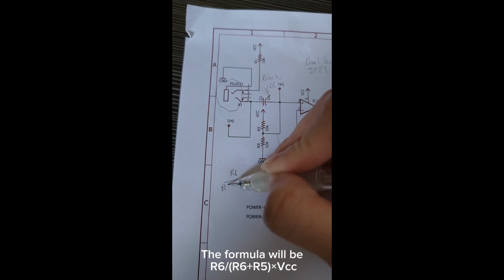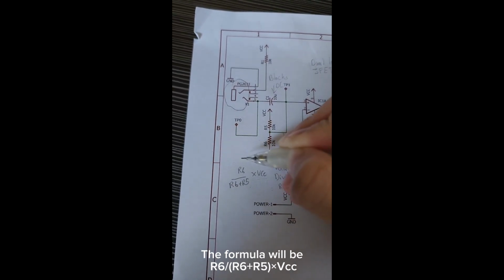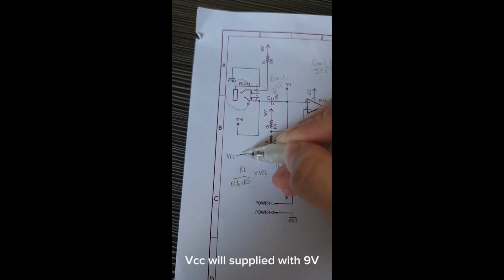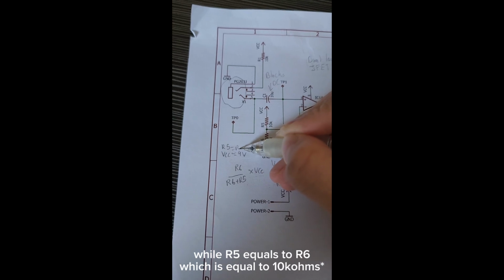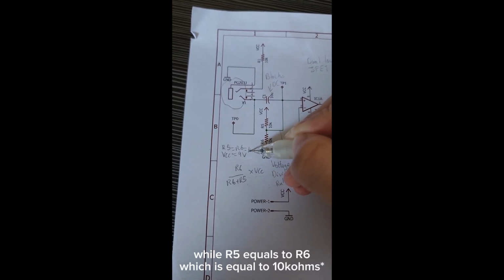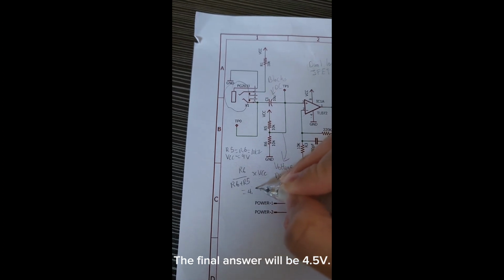The formula will be R6 over R6 plus R5 multiplied by VCC. VCC will be supplied at 9 volts, while R5 equals R6, which equals 10 kΩ. The final answer will be 4.5 volts.